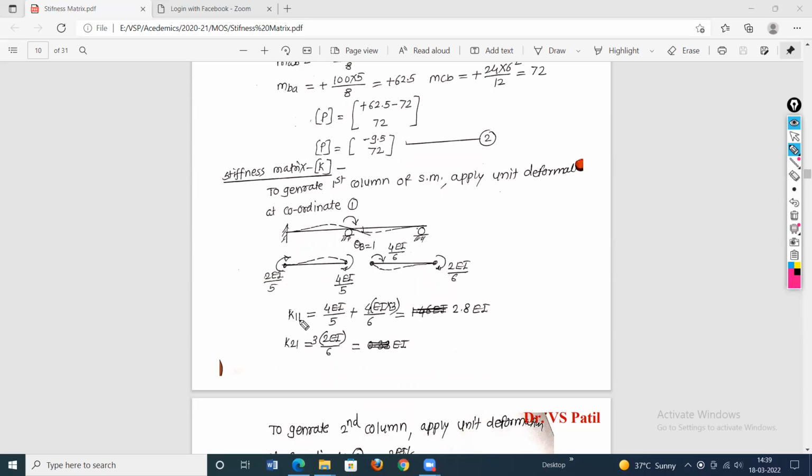So while calculating the element, wherever the second part comes, whenever the EI term of the second part's moment of inertia comes, at that place you just substitute 3EI. For example, this is for part 1, whose moment of inertia is only EI. But this is for the second part, so substitute 3I. This is the only change.